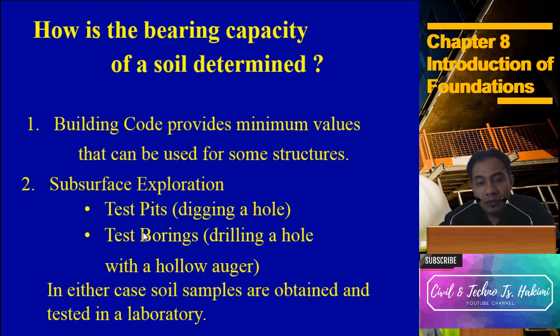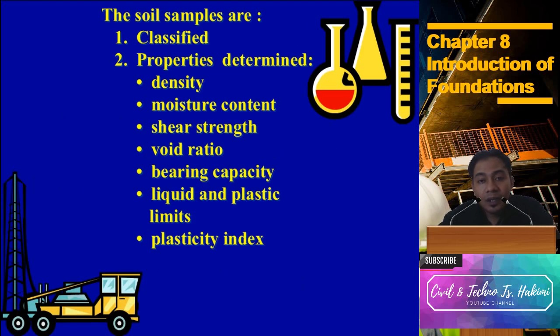Why for the test boring? Test boring is not used for the wide area, because we use the hollow auger to dig the hole, and then we can take samples to test at the laboratory to get the parameters of the soil to help in the design process.